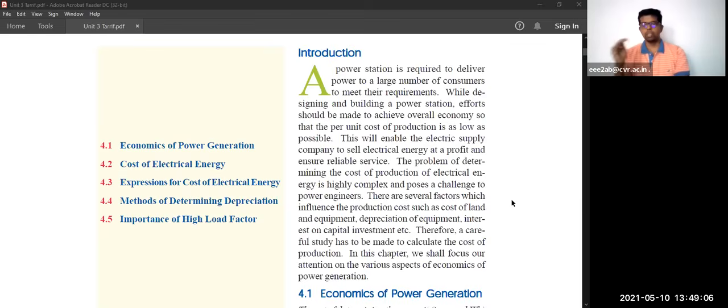The pH level of the water should be maintained constant, because the water becomes hard water. We have seen hard water versus soft water. If you take that hard water again to the boiler, the scale formation will be very fast, even though in normal water there might be some scale formation. If you are not treating the water and take it again to the boiler, the scale formation will be the most.